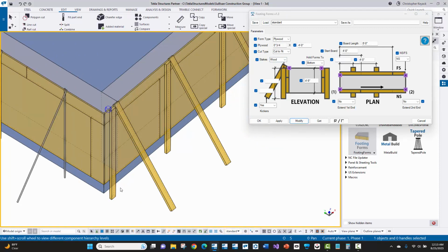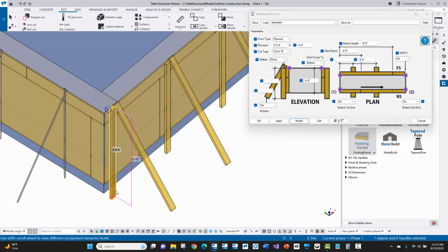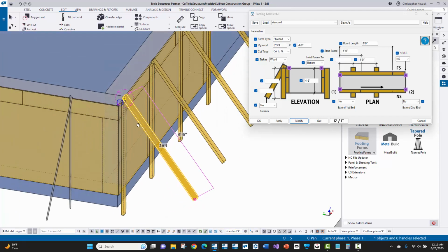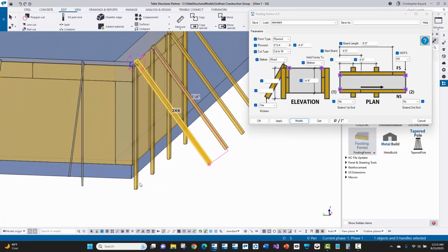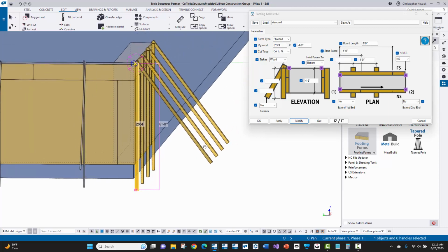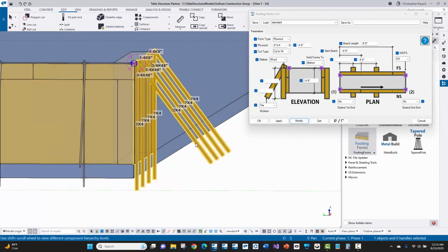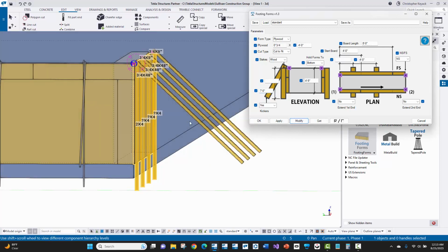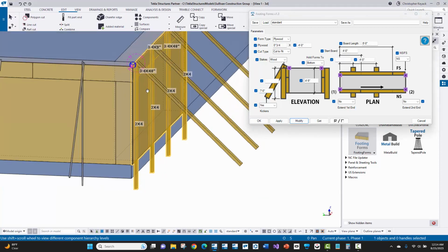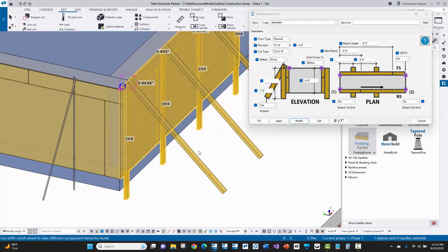Now what it'll do by default is try to make the stake and the kicker the same length. And you're probably wondering how that can be if this is at the diagonal. Well, the vertical stakes go just down further into the ground, and this is resting a little bit higher on the ground, but you have complete controls. So if you wanted to modify the specific length, let's say I wanted the kicker length to be 7 foot, I can modify, and you'll see that it calculates the geometry based on that stake length to place it here against the formwork and the wall.